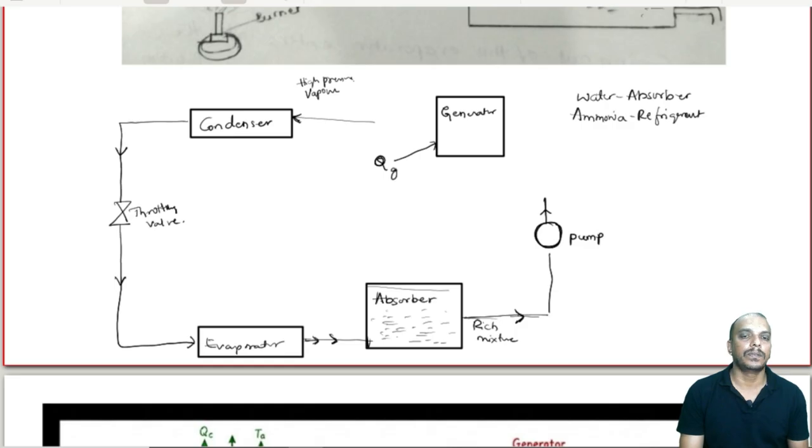So, let us call it QG, so that only ammonia is separated. Now, ammonia obviously is again back in gaseous state here, okay. Ammonia in gaseous state will be separated here. Then this will be weak. Even though it may have some ammonia gas, this will be weak. So, we will have a weak solution coming out from here.